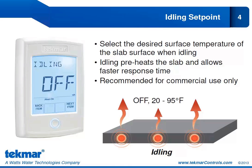We did discuss idling earlier in the training series, and we looked at idling and how we can use it to maintain a certain snow-free area ratio. So this would be operating our SNOMELT system to maintain a minimum temperature during the entire SNOMELT season. And the applications for doing so would be more commercial applications. Typically, you wouldn't use idling in a residential application because it will increase your energy usage dramatically.